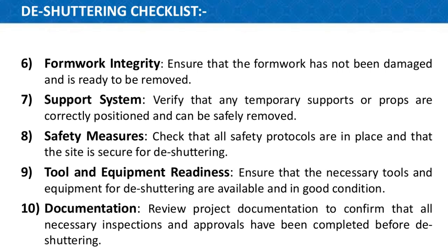as if it is a PT slab, you need to check from the PT vendor or the PT professional who are working in the post-tensioning work. So they will check and they will inform that the concrete has gained sufficient strength, and the PT tendon has also been stressed. Now it is safe for deshuttering. So you need to check from the PT vendor also.